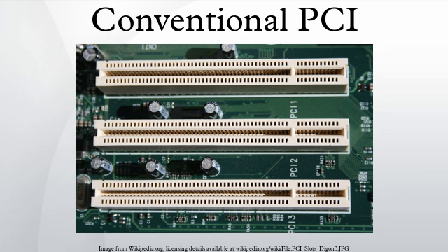Combining, merging, and collapsing. The PCI standard permits bus bridges to convert multiple bus transactions into one larger transaction under certain situations. This can improve the efficiency of the PCI bus. Combining: write transactions to consecutive addresses may be combined into a longer burst write, as long as the order of the accesses in the burst is the same as the order of the original writes. It is permissible to insert extra data phases with all byte enables turned off if the writes are almost consecutive.